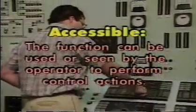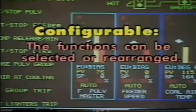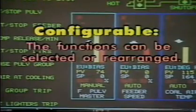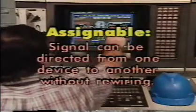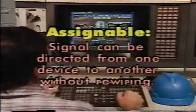Functions that can be used or seen to control process functions are called accessible. For instance, a set point change can be made to a process variable. Configurable means that the control functions can be selected or rearranged through the software configuration program or some method other than rewiring. Assignable refers to a feature that permits a signal to be directed from one device to another without the need for switching, patching, or changes in wiring.